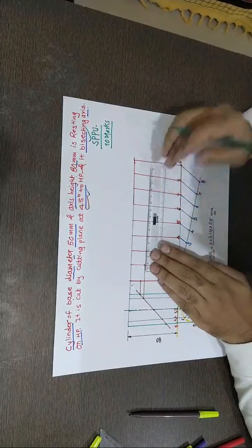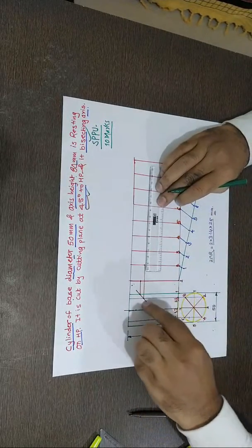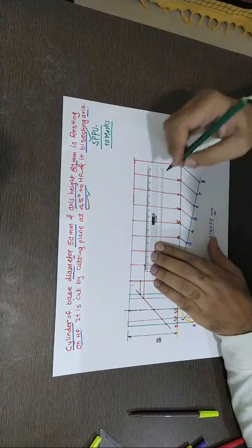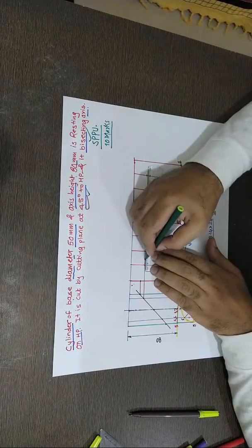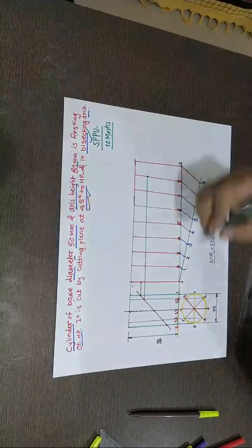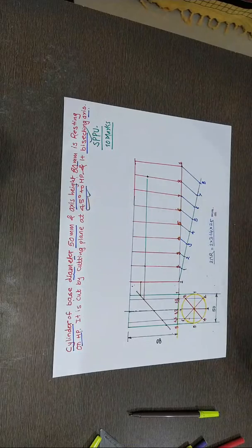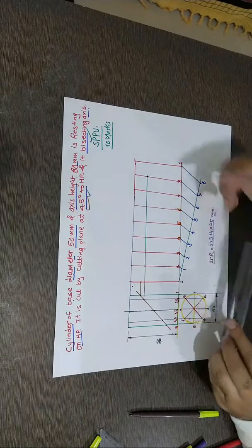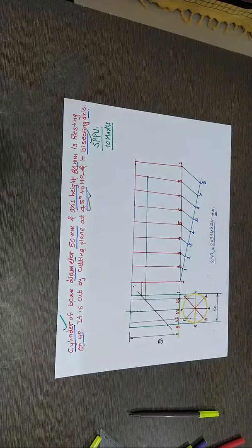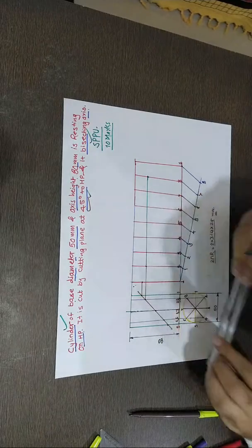Same is extended to point number 8, because you can see here clearly this is 2 comma 8, so intersection is extended here up to this is point 8. So I'll show complete line to avoid confusion. This is point number 8, this is point number 2, point number 1, and so on. You project all the points and join by the smooth curve. Remember, it's a cylinder, so it is not having edges for development. It's a curved surface, smooth curve. So I'm now joining all the points.